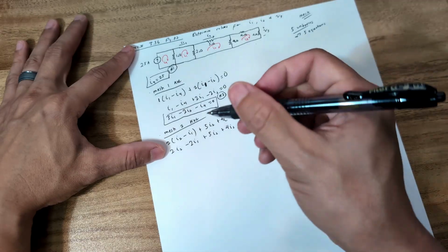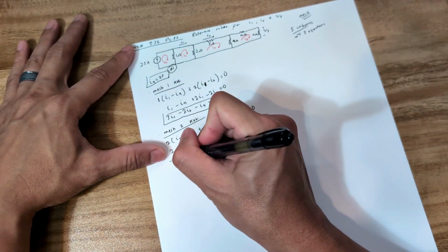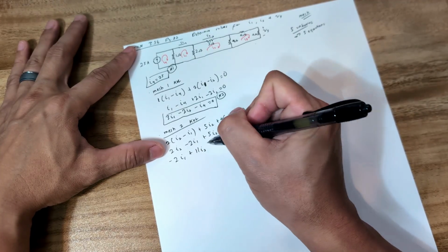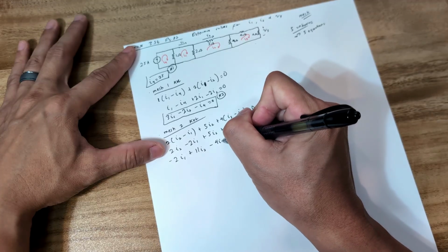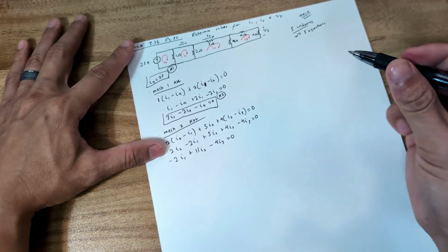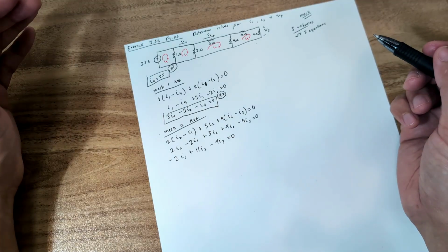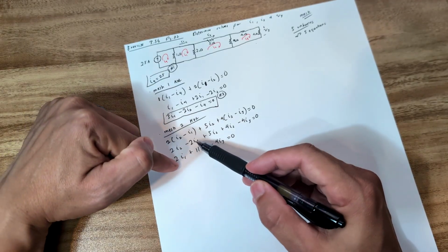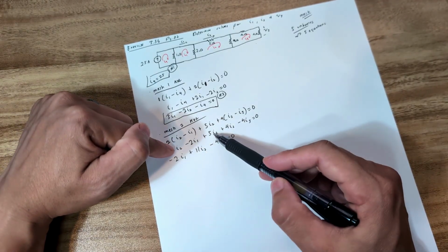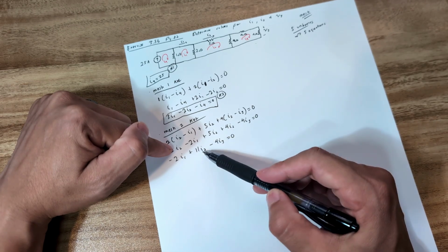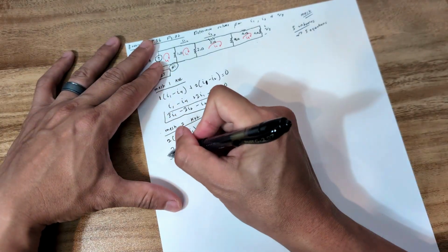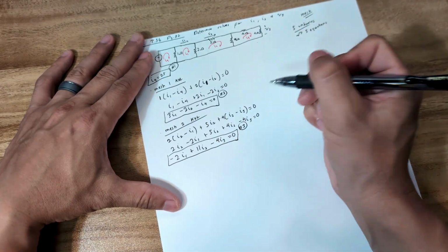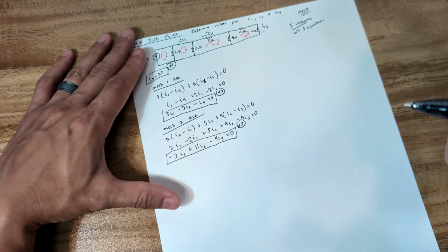And then combining like terms, we'll get our third equation, minus 2I1 plus 11I2 minus 4I3. You always want to double check, make sure that you have the proper work. It's so easy to make mistakes if you're going fast. And so again, I'm double checking, minus 2I1, 2 plus 5, 7, plus 4, 11, 11I2 minus 4I3. And that gives me my third equation. I need 5 equations because I have 5 unknowns.